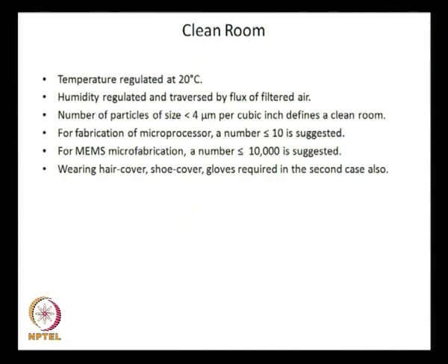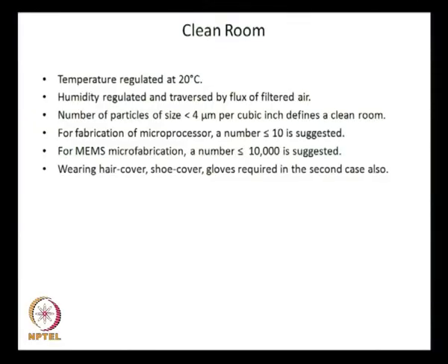So, what this means is that the clean room required for microfabrication of a MEMS device may not have to be the same as the clean room required for fabrication of a microprocessor. Still, for MEMS microfabrication you need certain cleanliness, and wearing hair cover, shoe cover, gloves, etc. are required, and of course the other conditions have to be satisfied.